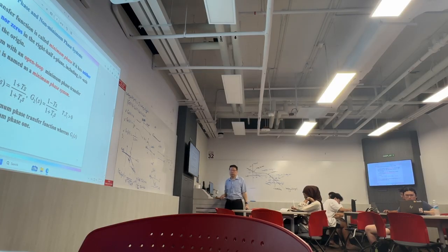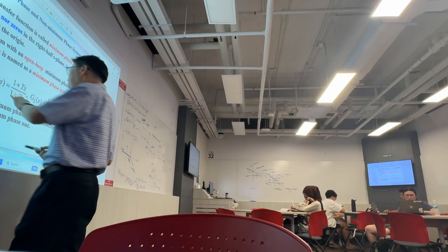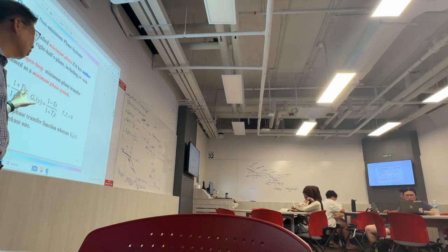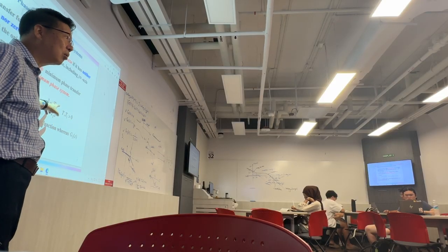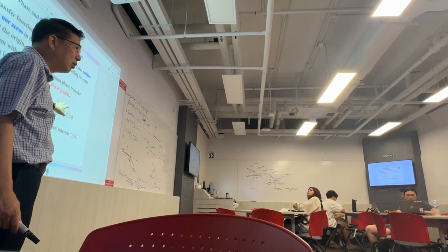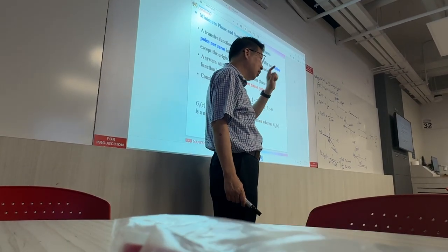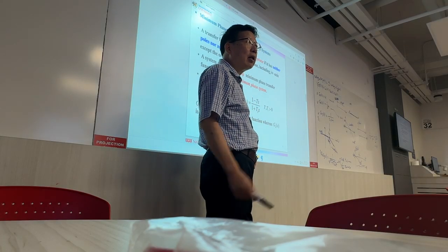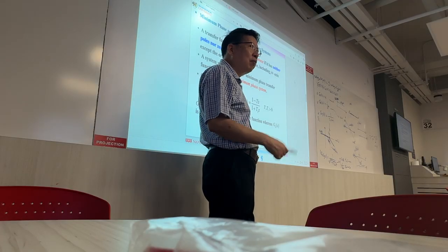Minimum phase and non-minimum phase are different in the sense that for the minimum phase, you see all these basic factors with pluses, no minus. Once you see a basic factor containing a minus, this is a non-minimum phase. Last week, in the last tutorial question, part A, we had the minus 1, and that required a lot of explanation on the phase, right?